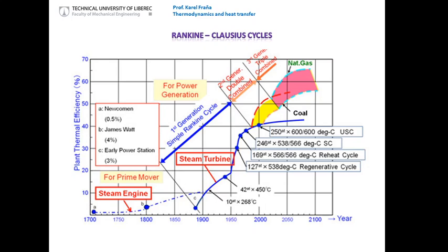You provide the first mechanical work, which is possible to use for the electrical generator, and the waste energy in the form of heat you can after that use for the classical Rankine cycle. This combined cycle enables you to increase efficiency significantly. That means this kind of power plant can work slightly above 50%. This is sometimes called the second generation.